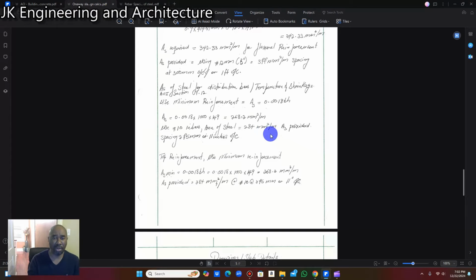So we're going to talk about our top reinforcement now. Remember I've said we use the top reinforcement in this instance for cracking. It's not a continuous slab. We are not only designing one slab. If it was a continuous slab, then we would have to calculate the moments at the support. But I'm going to do that in a separate video to show you how to design a one-way continuous slab. Somewhat different from what we are doing here, but basically the same.